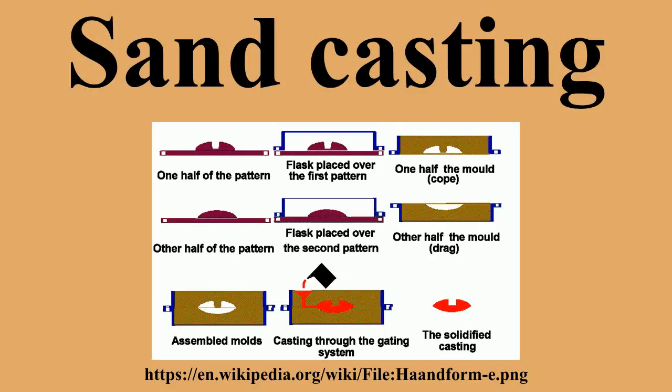Silica is the least desirable of the sands since metamorphic grains of silica sand have a tendency to explode to form submicron-sized particles when thermally shocked during pouring of the molds. These particles enter the air of the work area and can lead to silicosis in the workers. Iron foundries spend a considerable effort on aggressive dust collection to capture this fine silica.